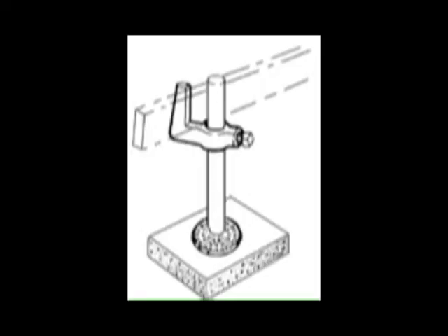If you have a larger slab, it may not be possible to do the screeding in one pass, in which case you can break out the slab into sections and put temporary screed posts in place. Now, a screed post is basically a concrete stake driven into the ground or set on a pedestal, which then has a screed hook coming off of it. The hook can be adjusted vertically up and down on the stake to adjust for the correct level. You then put a 2x4 or a pipe or whatever you want to use as a side screed level, and you run your screed board back and forth as we showed you earlier in the screeding of the concrete.